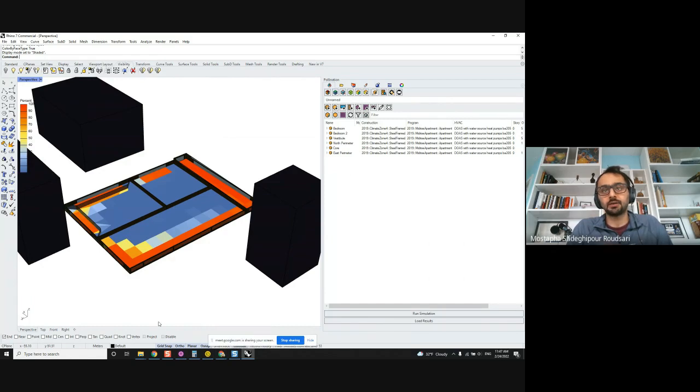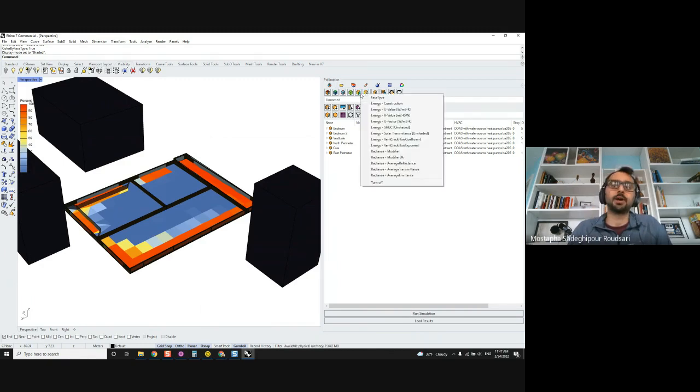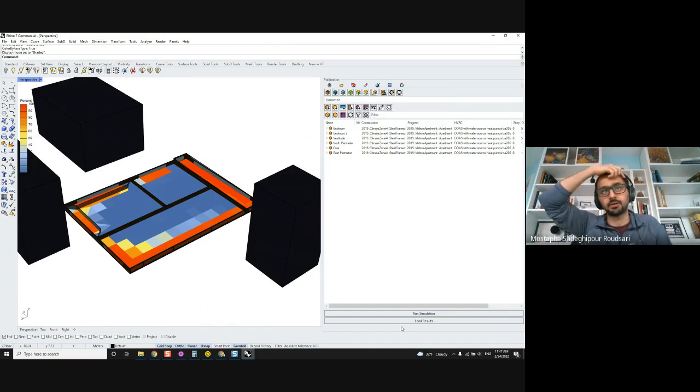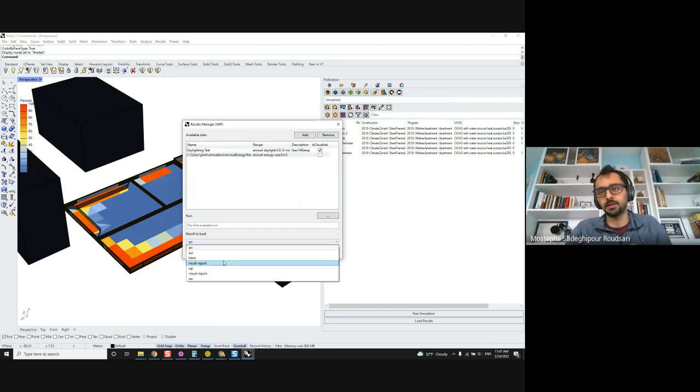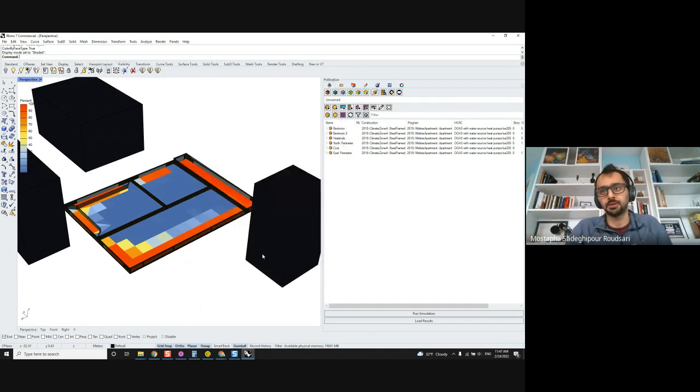On our side, right now, we have color by for all the inputs, but we haven't added color by the output that comes from the simulation. So you can use color by for face type and color by for room to check all the inputs in the model before running the simulation. But what you're talking about is basically, instead of coloring grid, coloring faces using the output of simulation. For now, you have to use that OpenStudio measure.